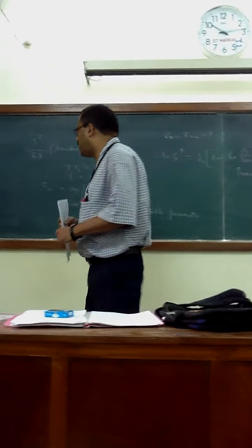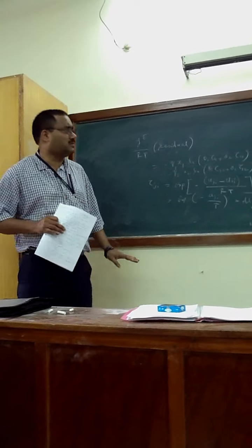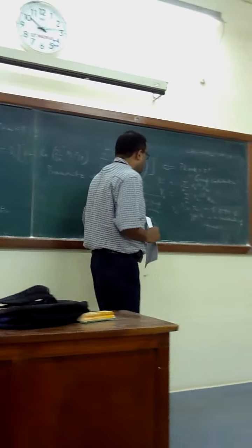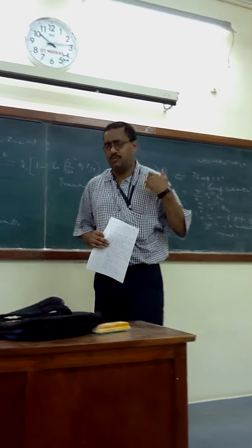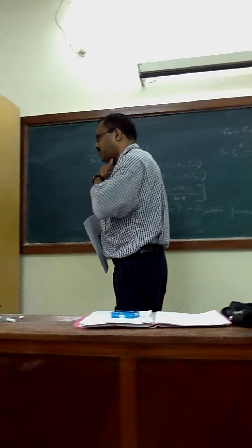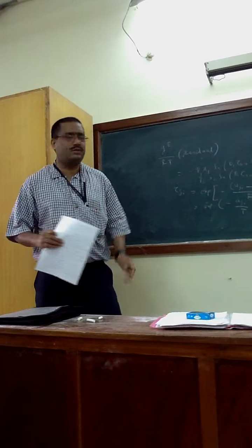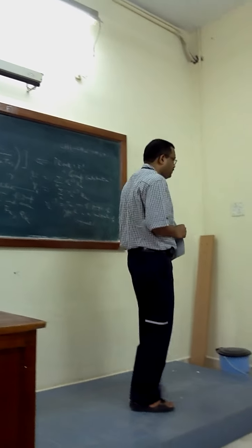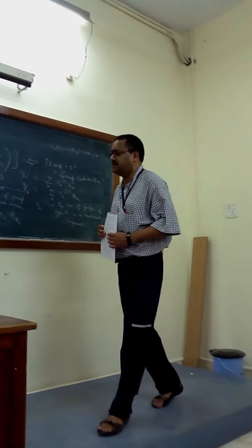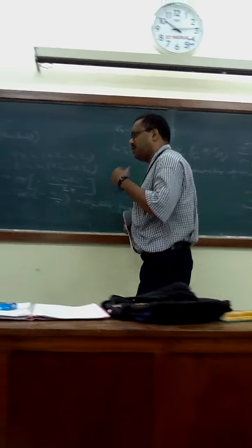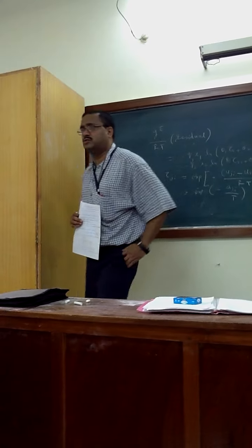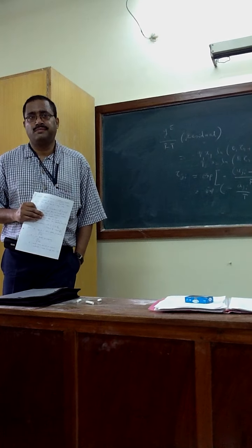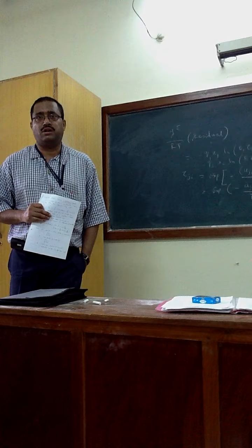So next we will go to UNIFAC. So UNIQUAC is over. This is the residual part we have done. The question was Ri and Qi. Small ri and qi are very simple if you have an inorganic solvent, but for an organic solvent, we will talk about the structural parameters. We will talk about the group contribution. Then small ri and small qi can be effectively estimated. After estimation, you calculate the combinatorial part, you calculate the residual part, you get the UNIQUAC calculation. Done. Right? So Ri and Qi are actually in the combinatorial part, not the residual part.